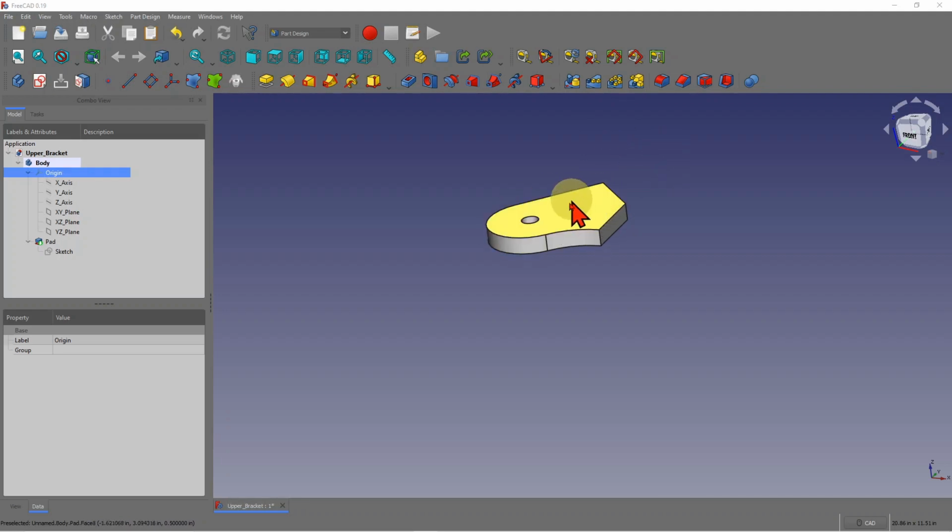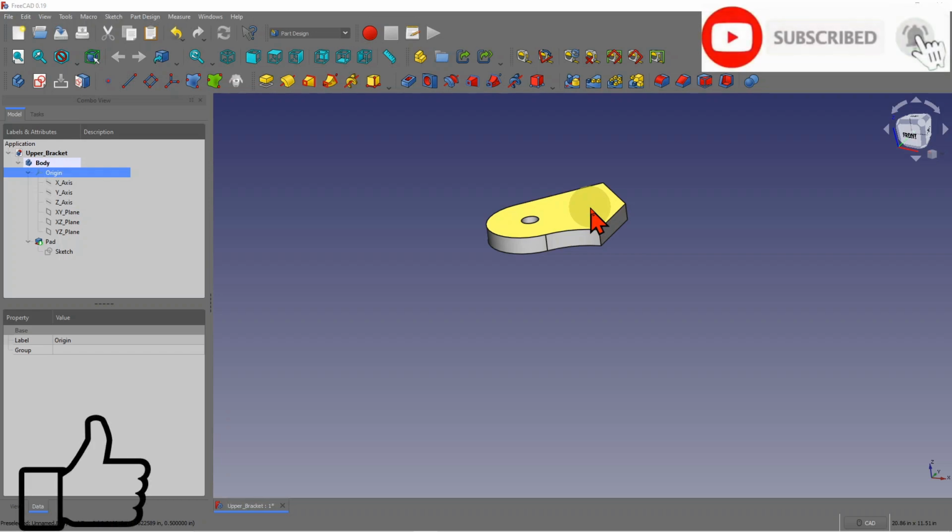Now the easiest way to do that is to pick this surface and create a sketch, but I'm not going to do that because in FreeCAD we have this problem called topological error, where the current FreeCAD versions keep track of all these faces and bodies in a numbering scheme, and that can get messed up, and that can cause problems down the road, because if this number changes, whatever you create on this face gets essentially screwed up, and we want to avoid that, okay.